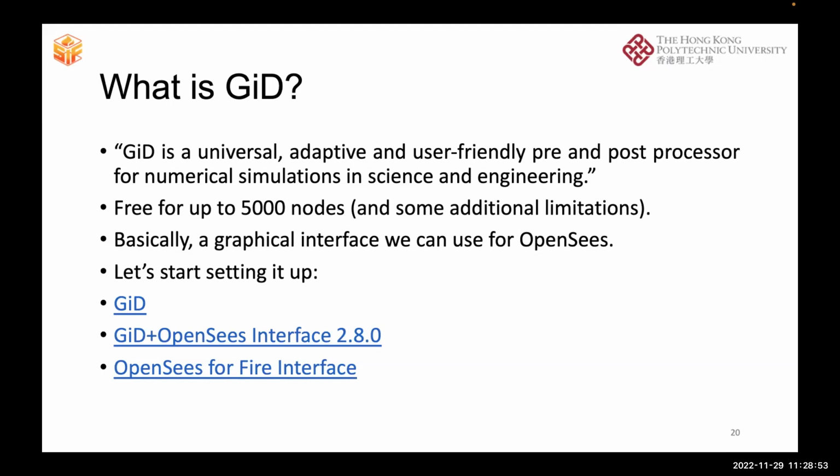Okay, yeah. So what Sensei has just asked is, when they do meshing, they need to have a denser mesh near the fire because the thermal behavior is more interesting and it's more difficult to do the heat transfer analysis. Can you do that in OpenSees? The short answer is, unfortunately, right now, no. That's because our mesher is super simple. You give it a number of elements to mesh in one direction and the number of elements in the other direction. I think Liming, yeah, I can actually explain.